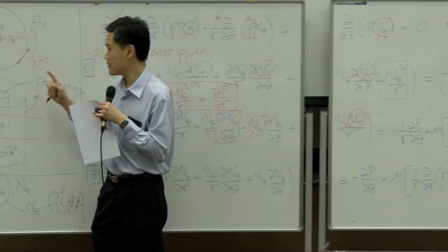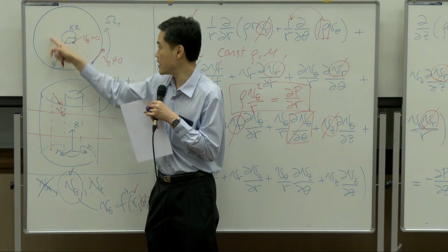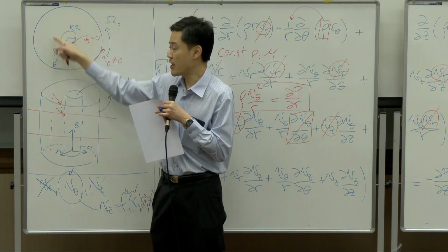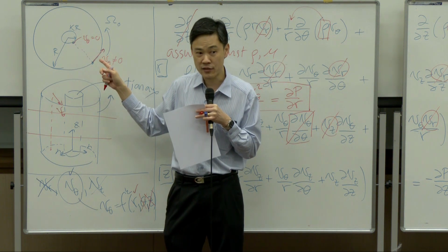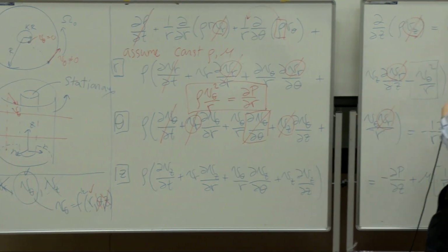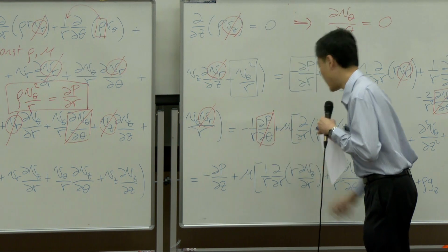Let me ask you this. It rotates like this. The flow goes in this direction. Does it mean pressure changing in angle? No, it does not. Okay? So pressure does not change with respect to angle. This term will be dropped. The whole term will be dropped.